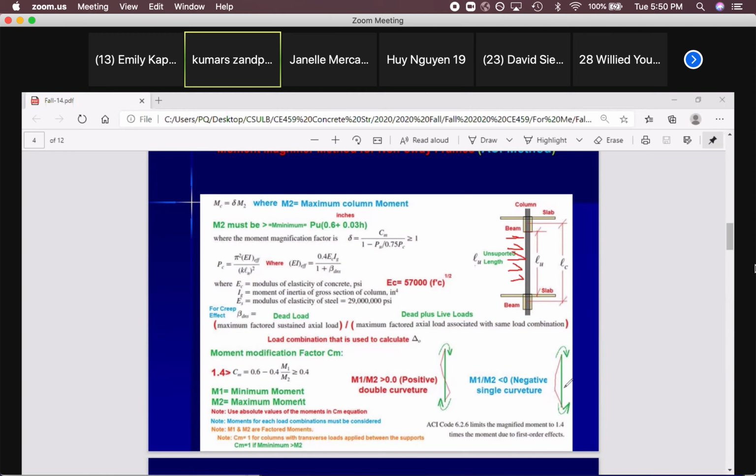You have to design your columns for all your load cases separately. Do not combine the load cases. Load case 1, complete design. Load case 2, complete design. And for each one, you might get different moment direction based on the moment analysis for that frame.